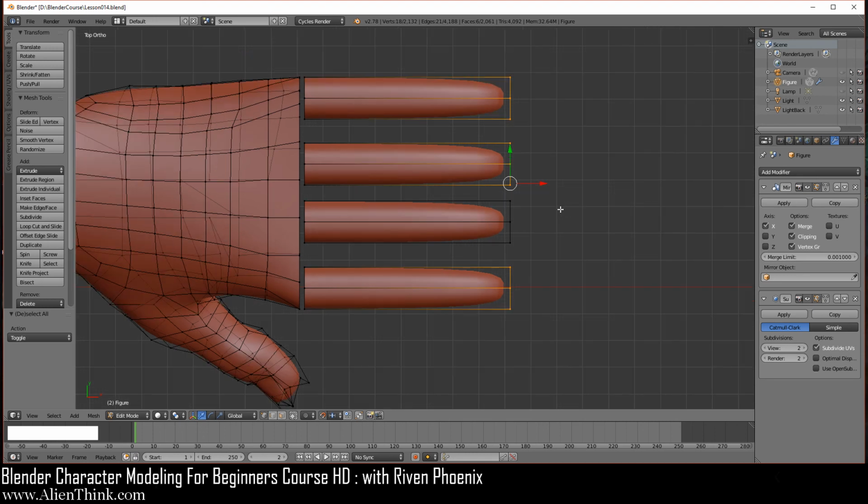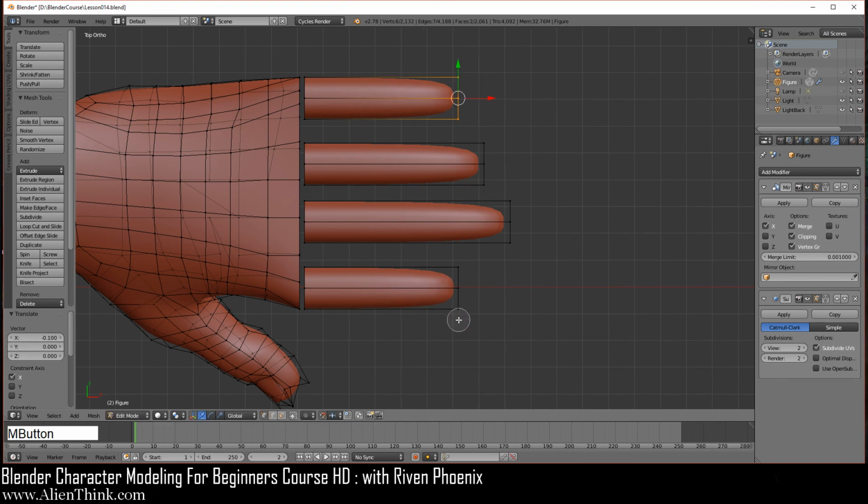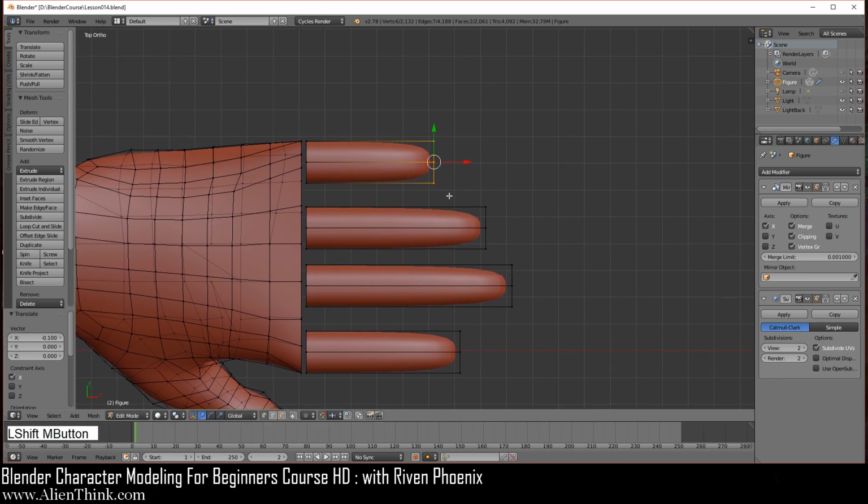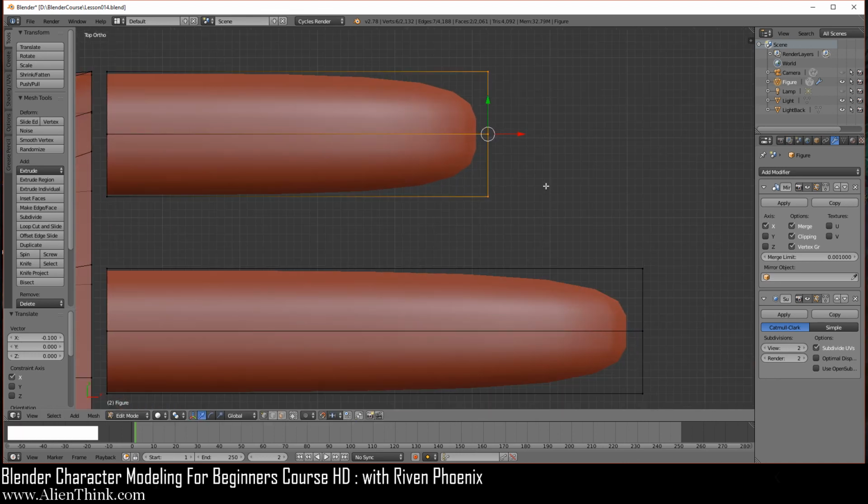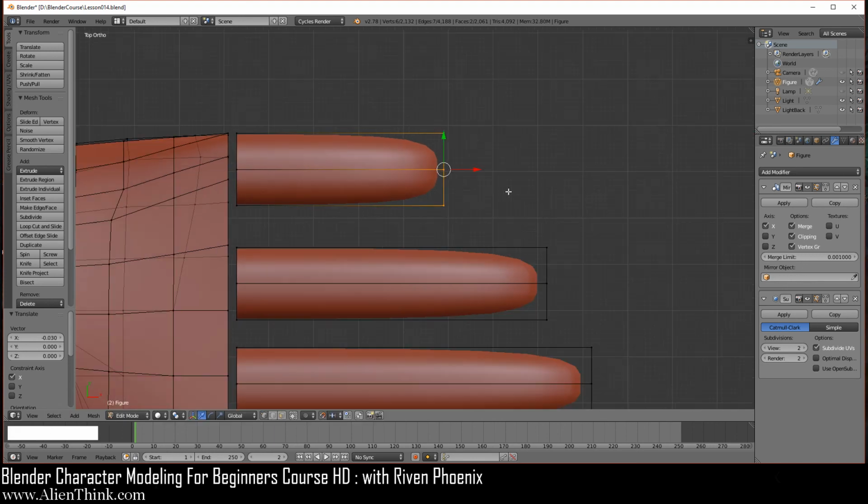Now you have to just zoom out so you don't get the smaller grid units. You're going to take it in one time over here. Press the C key, do the middle mouse button to deselect, right click to get out of it, bring it down one time over here, press the C key, middle mouse button, right click to get out of it, and take it over here. Now do shift middle mouse button to pan over here and zoom in to get the smaller grid units. You're going to bring this in 1, 2, and then 3, and then A to deselect.